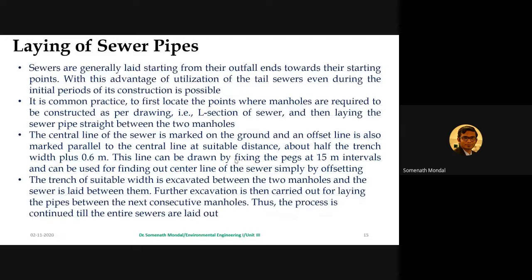Now, with this, the advantage is that utilization of the tail sewers, even during the initial periods of construction, is possible. So that is very true. If you start from the end, you have all the flexibility to maintain, and a lot of flexibility to play with the gradient, and at the same time to play with the discharge, or if there is a certain gradient change, how to accommodate that. Those things can be done.